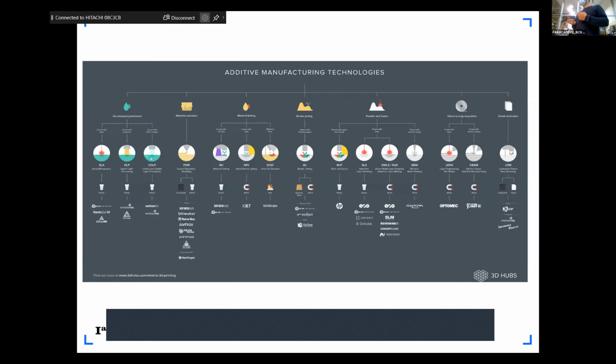So what we are doing is paste extrusion, that is PE modeling, basically. PEM is when you have a material in a certain state, usually semi-liquid, like a paste, that hardens by a chemical reaction or, in the most common case, dries up. For example, the house is full of clay things. We print a lot with clay and concrete, and today we will also do smashed potato printing, just because it's slightly cleaner than clay and easier to mix.